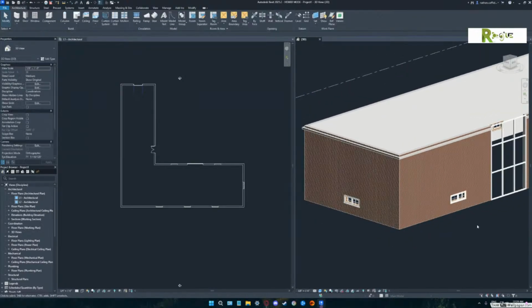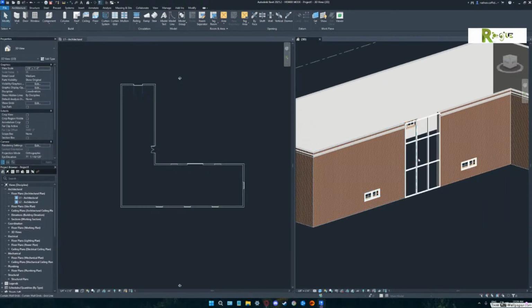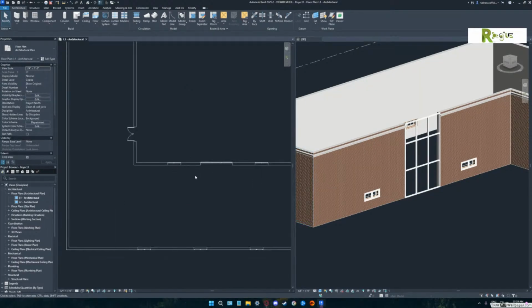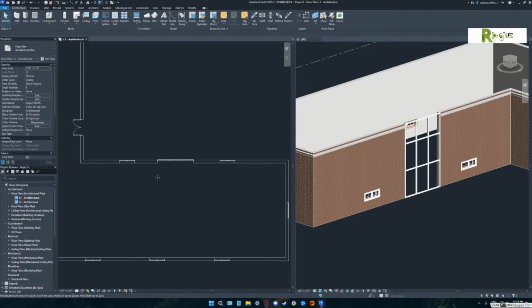Do you remember how we split that one wall and turned it into curtain wall? Yes. Right. It's in the corner of our view. It's that big piece of glass curtain wall. What I want to show you is another thing about walls. So if in plan view, you zoomed into that area, right? Perfect. What we did was we actually have three different walls there, right? We have one on the right, and then the curtain wall, and then the one on the left. Well, you don't actually have to split that to do that.